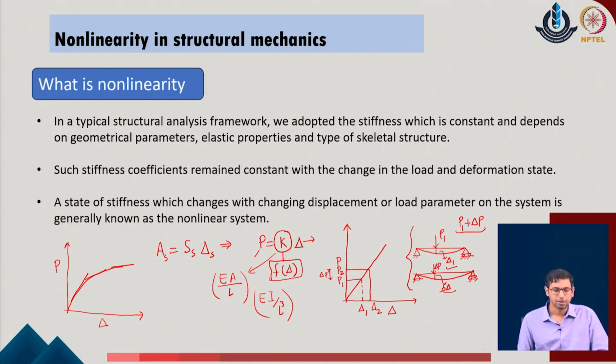But the moment the material coefficients, say the elastic property of the system, or the deformations in the system are successively large, which makes the system stiffness a function of the displacement itself, then the condition of nonlinearity is introduced in the problem. This is the condition where the stiffness changes with the changing displacements or load parameters on the system, and this is typically known as general nonlinearity in the problem.